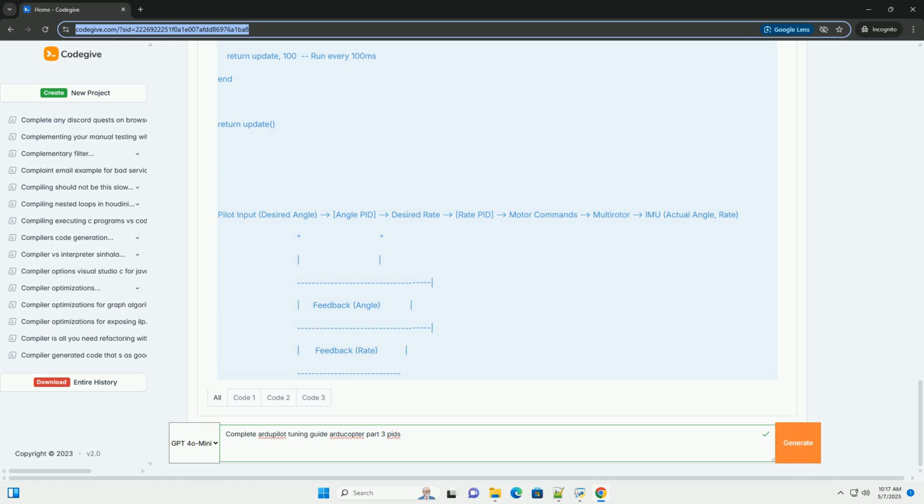Code snippets, for analysis, not direct modification. Important: modifying ArduPilot code directly while the system is running is extremely dangerous and can lead to crashes. The following snippets are for understanding the logic, not for making live changes. Use the parameter tuning interface in your ground station. If you want to modify the code, you have to compile the software and flash it to the flight controller.